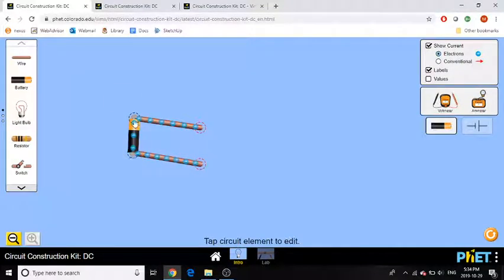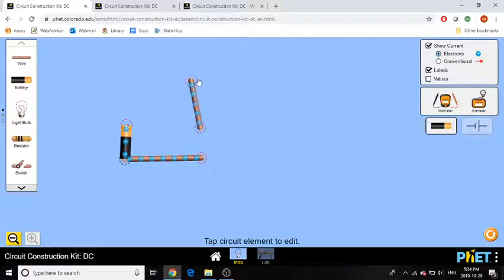You'll notice here these rings have gone black. That shows that it is properly connected. If your circuit isn't doing anything, and you're wondering why, make sure that all the joints are properly connected. You can also always disconnect them with the scissors. Once again, in the middle you can move the whole thing. If you just want to move an end, click the red ring and connect it. Now I'll grab my light bulb, and we now have our simple series circuit.